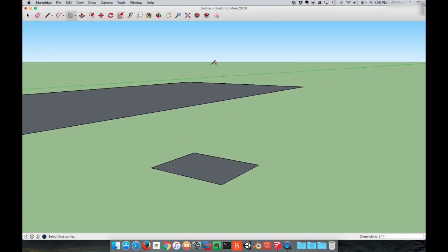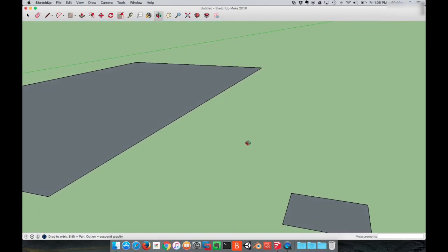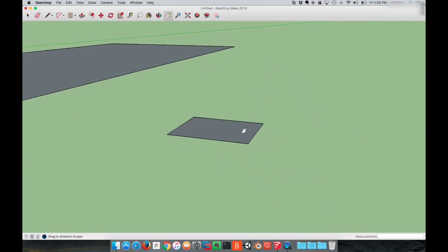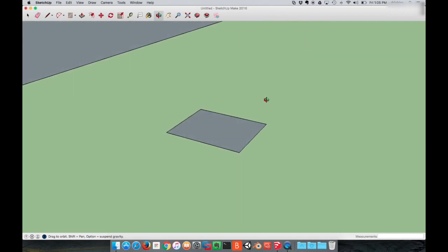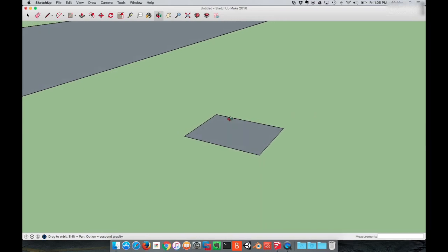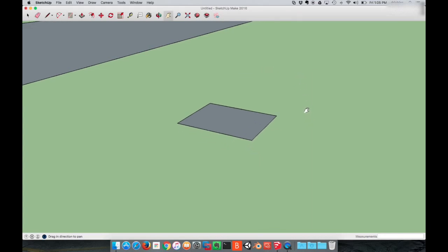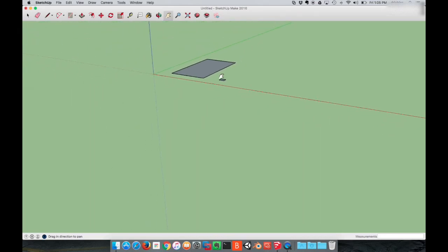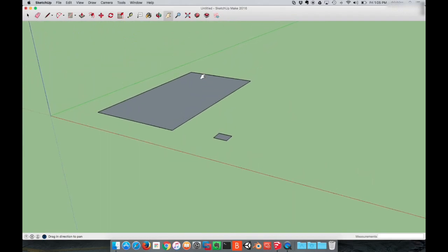I'll zoom in with my mouse wheel, use my orbit tool here to orbit around. You notice I don't go straight on it, so I'm going to use the hand tool and move the camera to the side. Go back to my orbit tool. And as I was saying, hotkeys, I just hit the H key, the O key to switch between those two. The R key will then also draw my rectangles again. SketchUp has all of the hotkeys listed elsewhere.